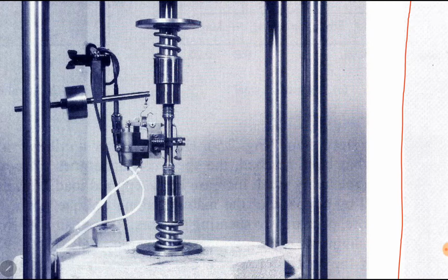After converting the units, like we have converted millimeter squares into meter squares, kilonewton into newtons, and gigapascal into pascals, we can calculate delta D, which becomes 300 into 10 power minus 6 meters or 0.3 millimeters. Since the member CD is under tension, the point D will definitely move downward under tension. So a downward sign has been shown with delta D.